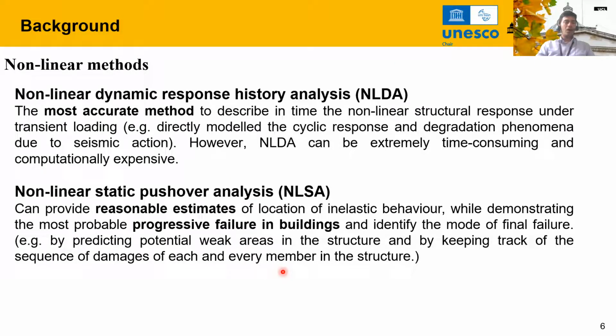So by now, we have already understood that the nonlinear methods are the ones we need to use for analyzing our structures under extreme loadings, for example, earthquakes. Within nonlinear methods, we have the nonlinear response history analysis, also called NLTHA or nonlinear dynamic analysis, and we have the nonlinear static analysis, which we call nonlinear pushover analysis.